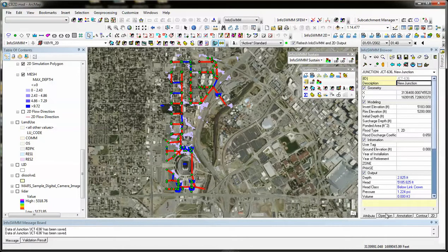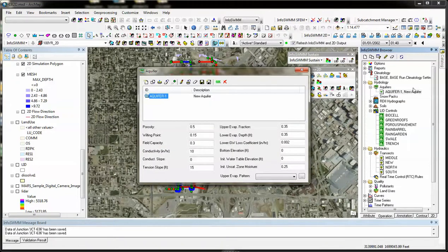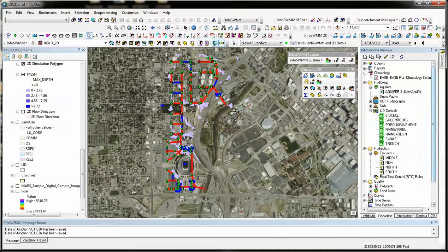In addition, we also have a very good climate change model. You can predict, using the SWMM-CAT from EPA, the changing temperature, evaporation, and rainfall over time, and simulate in your continuous simulation. We also have linked groundwater models. So if you have a BMP or LID at a storage node, it can link to the groundwater and you can model recharge.